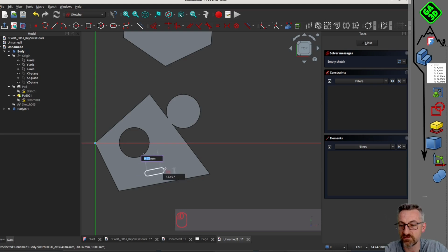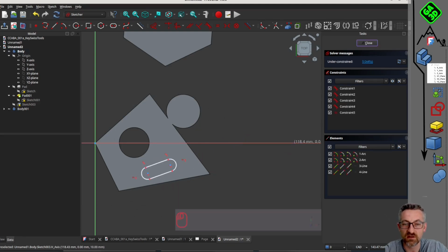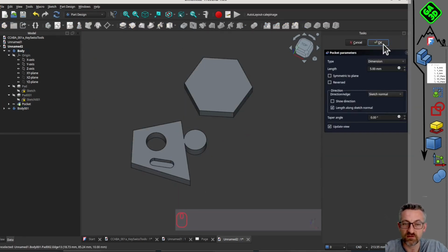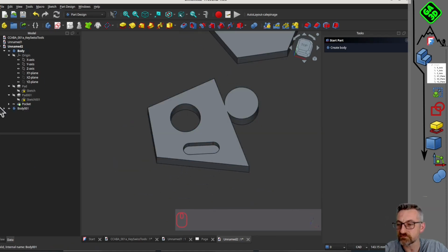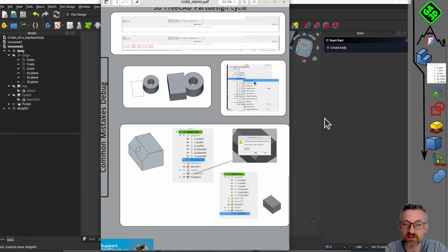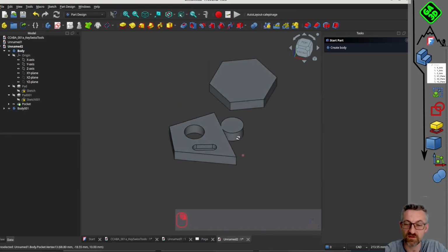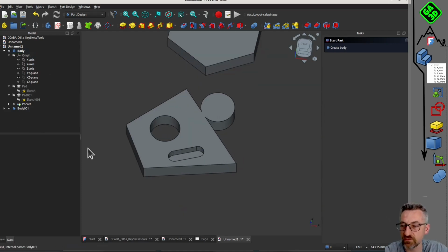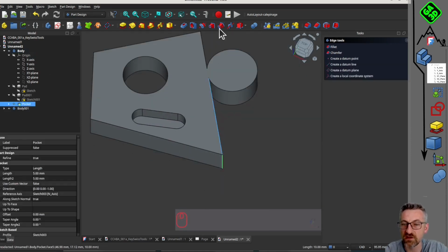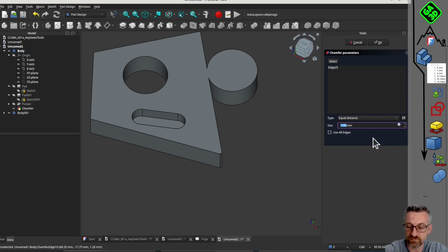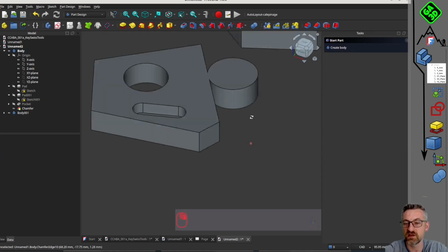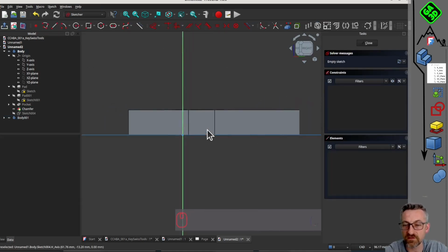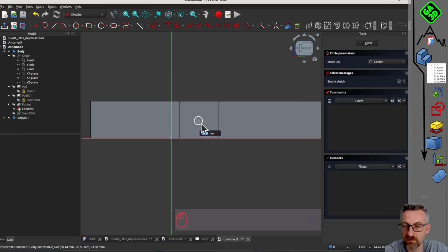And now you want to work on it. Work on this one, so you click on it. You get messages you don't understand, etc. But the mistake you made is that now you're on the body of body 1 here. If you want to work on this body, very important, you activate it there, you can click on it and then add a function. It's typically a beginner's mistake, so there you go.